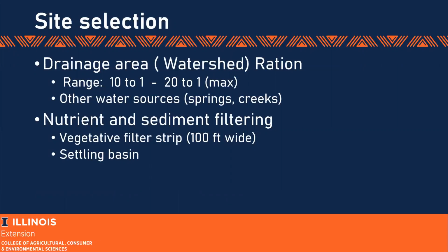If we're talking about a 1/4 acre pond, that means somewhere between 2.5 acres and 5 acres is that ideal watershed size. So as we look at that first picture, you've got that area up above the field there, and that was close to a 1/2 acre pond, and they had about 8 or 9 acres draining into it. So there's kind of your sizing that you're looking at.